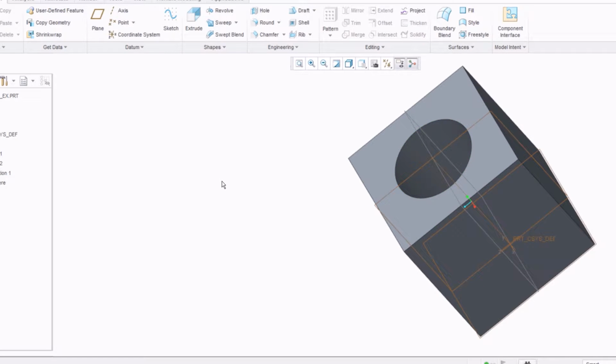Now, the perk with using the extrude versus a sketch then extrude is that you actually have less features in your feature tree. You'll find out in later parts as things get more complicated, you'd like to reduce the number of features, make it easier to read and understand. So having this one sketch here, while it doesn't look bad now, after having 10 or 15 of these, you can imagine it's going to get kind of confusing. You'll have a long list that's really unnecessary. Okay, so we'll go ahead and move on from here.